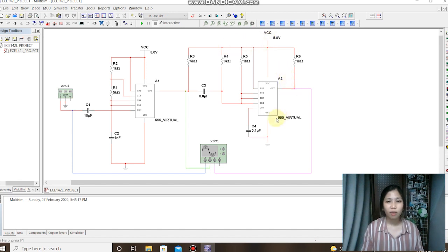This circuit diagram shows how a 555 timer IC is configured to function as a basic monostable multivibrator. A monostable multivibrator is a timing circuit that changes state once triggered, but returns to its original state after a certain time delay. It got its name from the fact that only one of its output states is stable. It is also known as a one-shot.